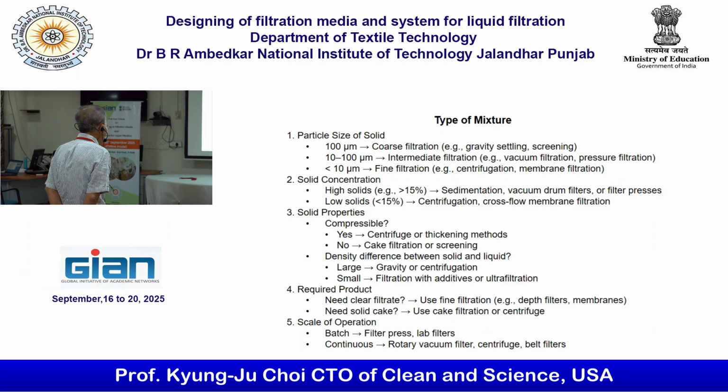cross-flow membrane filter. What about the solid property? Is it compressible or not? If it is compressible, then you have to choose centrifuge or thickening method. You know, flocculant or coagulant, you have to use it. If it is not, then cake filtration or screening. What about density difference between solid and liquid? Large, gravity; small, filtration.